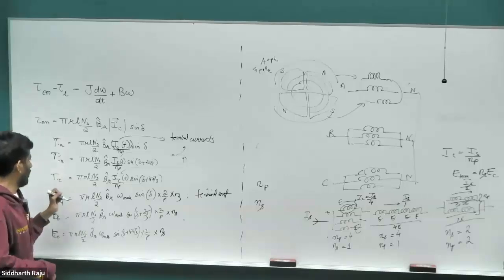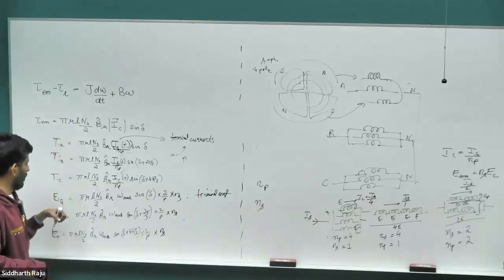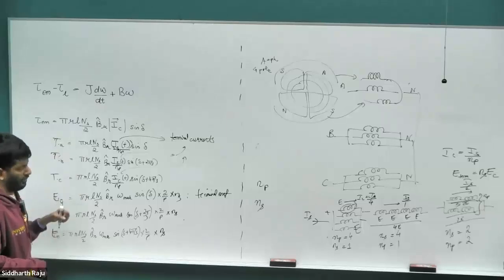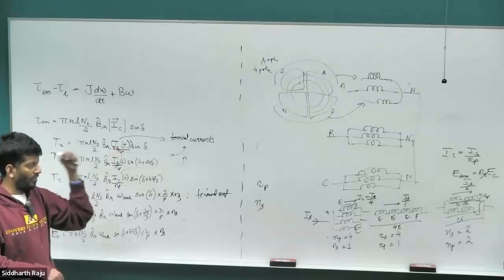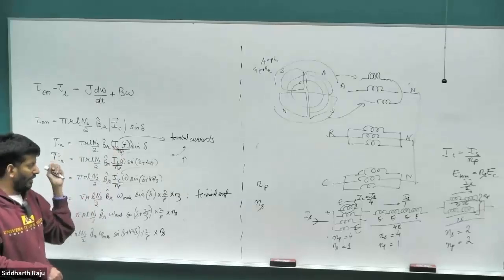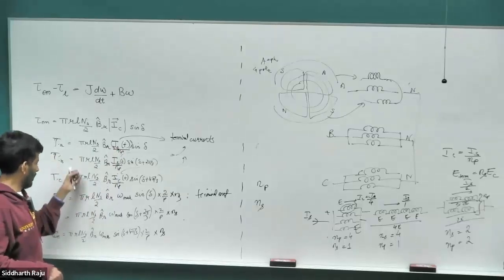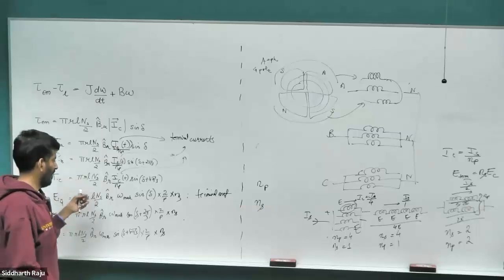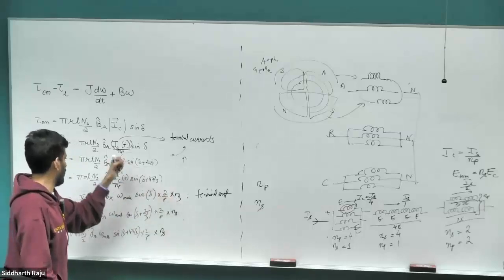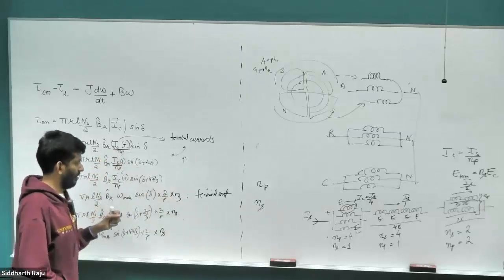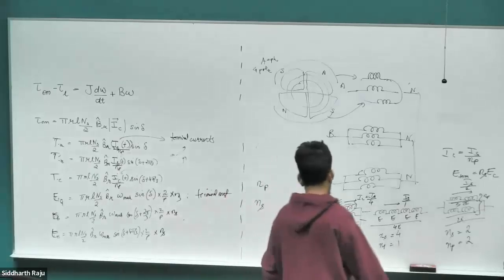I told you that the factor scaling the EMF must be the same factor that's scaling the torque. Right? Again, because of the power balance requirement, the mechanical output power must be the same as the electrical power, and that can only be satisfied if these terms have the same coefficients, Ke being equal to Kt. But clearly here we have two different factors scaling. We have some NS times 2 by P, and then we have division by NP here. So where is the missing term coming from?